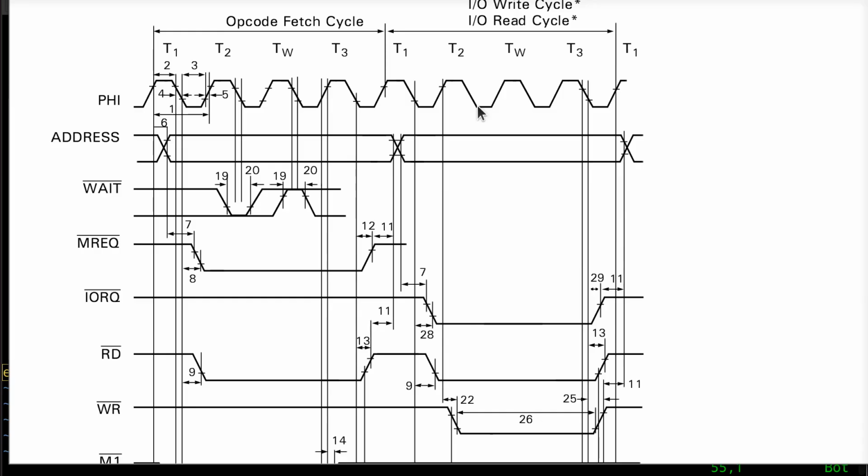Now it's going to stay in state 1 as long as there's a falling edge here and these two are both true. Then it'll get to the point where T1 will fall way over here, and then it'll go back into state 0 way over here in time for the next machine cycle. In other words, on this falling edge of T1 in the next cycle is when our state will end up going back to 0, because state only changes on the falling edges of phi, right?